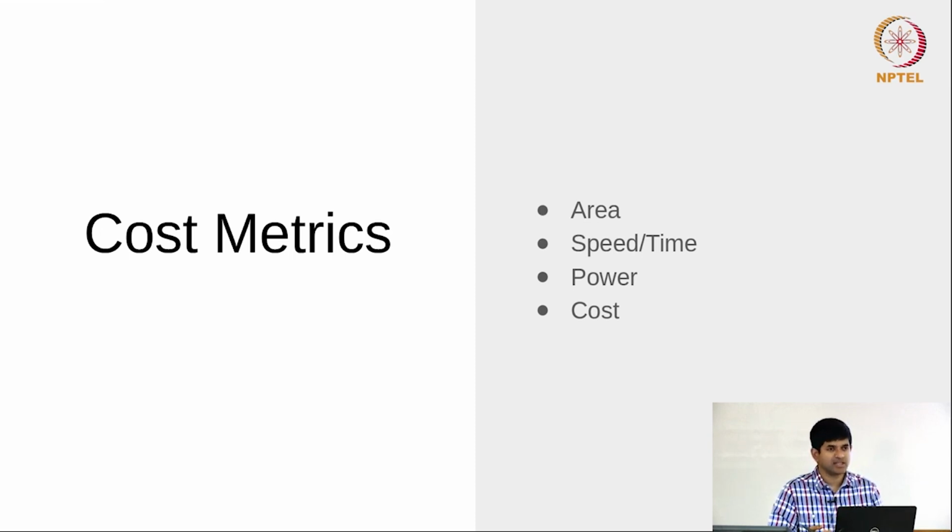Another variant of this is not just the power but actually the energy consumed, which means okay, I have a system with a certain power consumption, but if the thing gets over very fast, a fraction of a millisecond, then the total energy consumed is so small that I don't care, to the point where you might actually find that taking a big Intel Xeon processor and running some kind of image processing on it actually consumes less power than running it on a low powered mobile phone processor, or rather consumes less energy. Why? Because the Xeon is basically able to do it so fast that the total energy consumed is very tiny, right? Whereas the processor on the phone individually is taking much less power but runs for much longer, and the total energy that it consumes could be, not automatically is, but it could be, given the circumstances, more than what is actually consumed by a high-end processor.